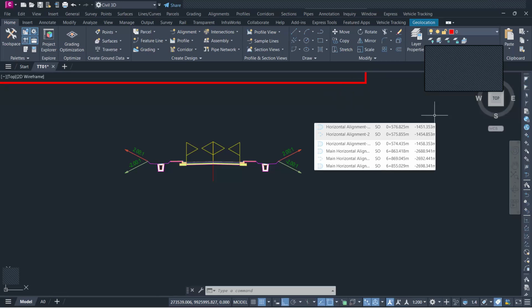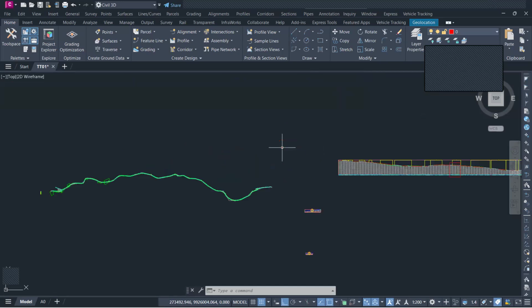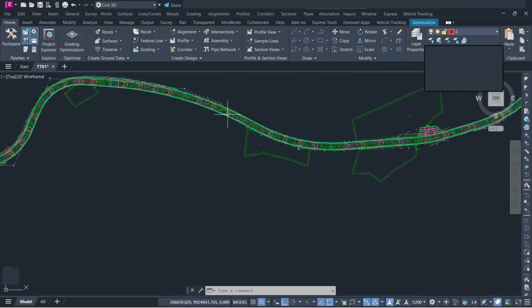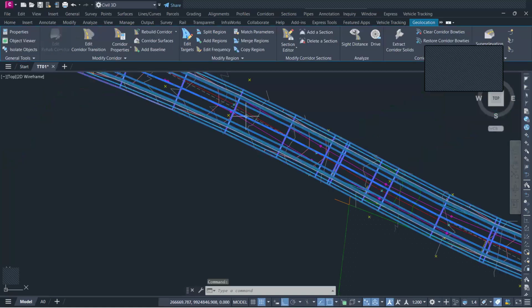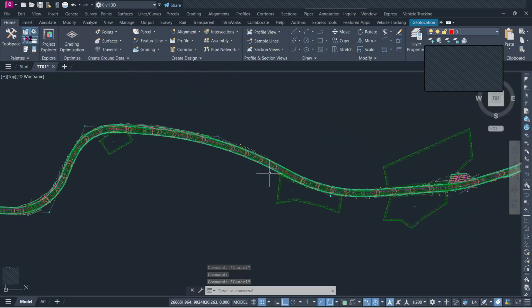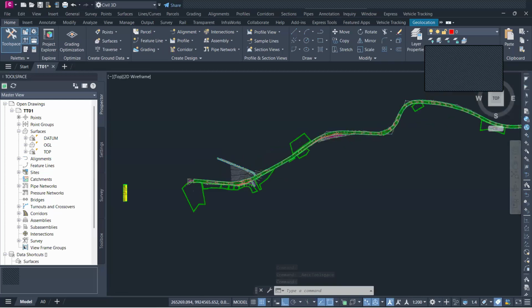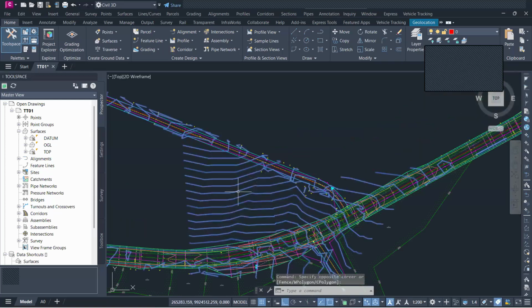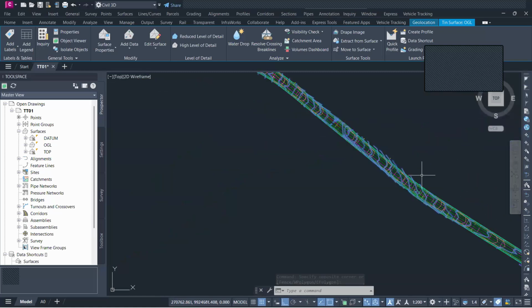Then after that, we are talking about now the actual computation using Civil 3D. We basically use surfaces. Surfaces help us in creating the design and in getting quantities. The first quantity takeoff that you did was for topsoil stripping. For example, let me see whether this engineer did it. I think they did not do it. Where, for example, you want to do the topsoil stripping of the entire corridor.